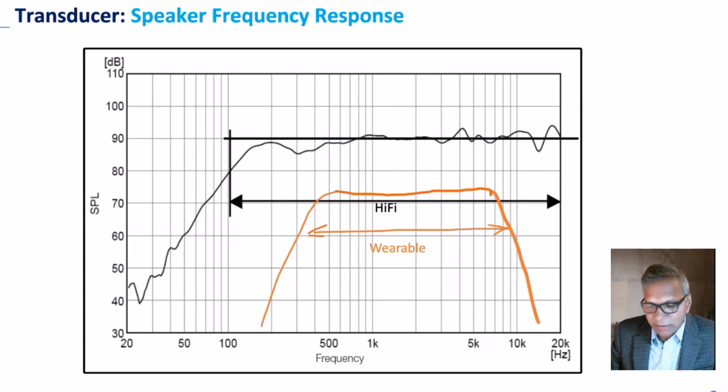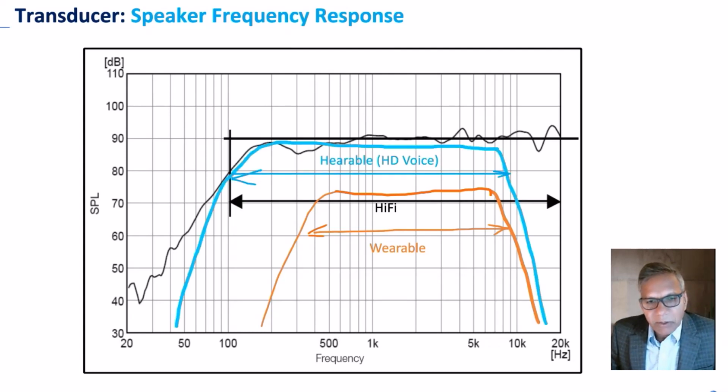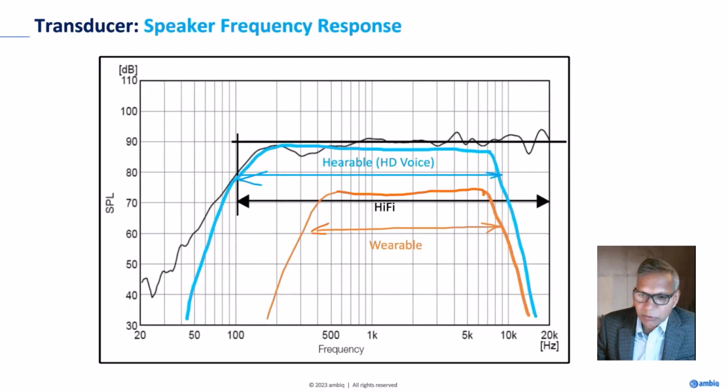depending on what kind of loudspeaker and acoustics they have selected. We take a frequency response of a hearable device, because hearable devices are sitting close to our ear. They can generate loudness, and we can get a desired frequency response without much distortion. The typical impedance, if we use a voice coil for hearables, is 16 or 32 ohms, and for wearables an 8 or 4 ohm load.